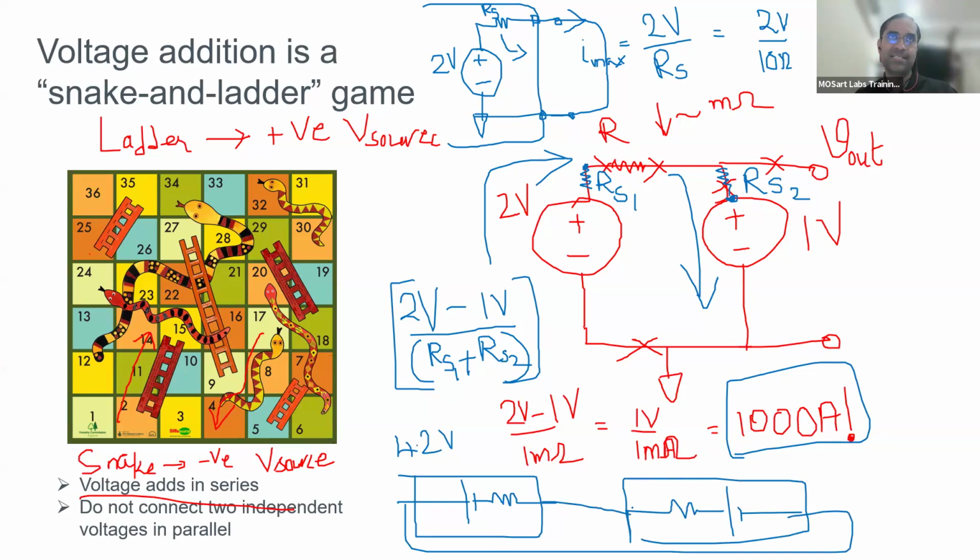Arcing you will see sometimes. Typically there is a sequence where you connect and disconnect, and you typically don't want to touch your positive terminal first. So you connect your grounds first, and then you connect your positive terminal. So there's a sequence to avoid arcing. Similarly, while disconnecting, you do it in the opposite way: you disconnect positive first, and then disconnect negative later. So it's vice versa.